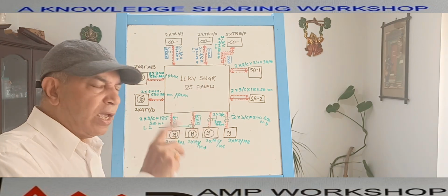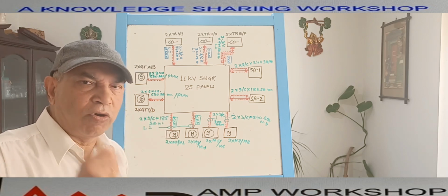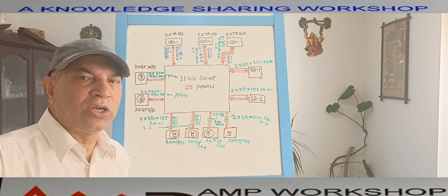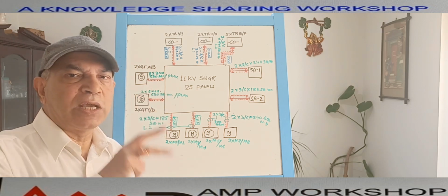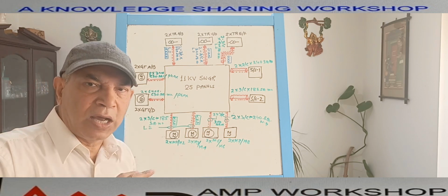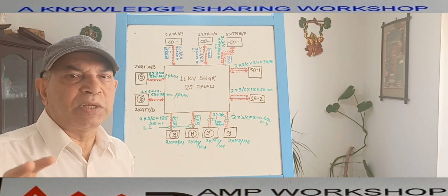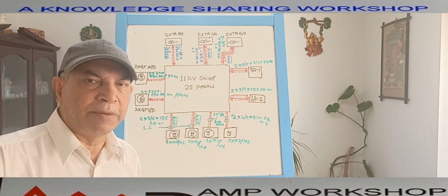So this is the way the cable block diagram is made, and it helps the site construction team a lot to lay the cable, to visualize overall how many cables there are and how the cables are to be laid, and what the various lengths of cable required are. That is also something we can show on the cable block diagram.